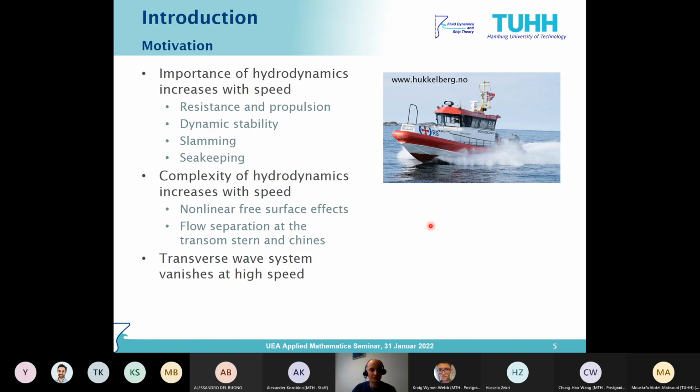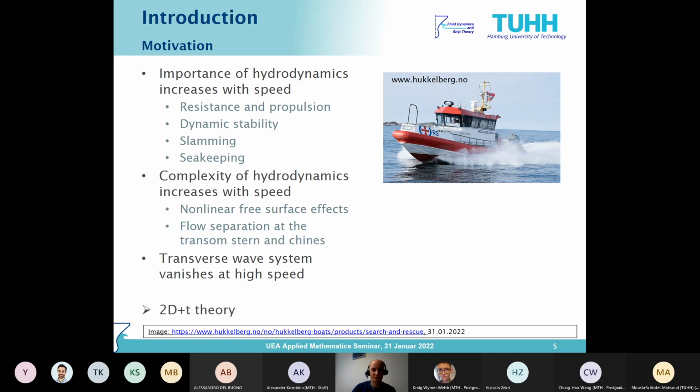Now there's another feature of ships going very fast, which is that the transverse wave system vanishes at high speed. This allows for a simplification that results in 2D+t theory. With this simplification, we can better account for those nonlinear free surface effects. So this is basically the motivation to use 2D+t theory for high-speed hydrodynamics.